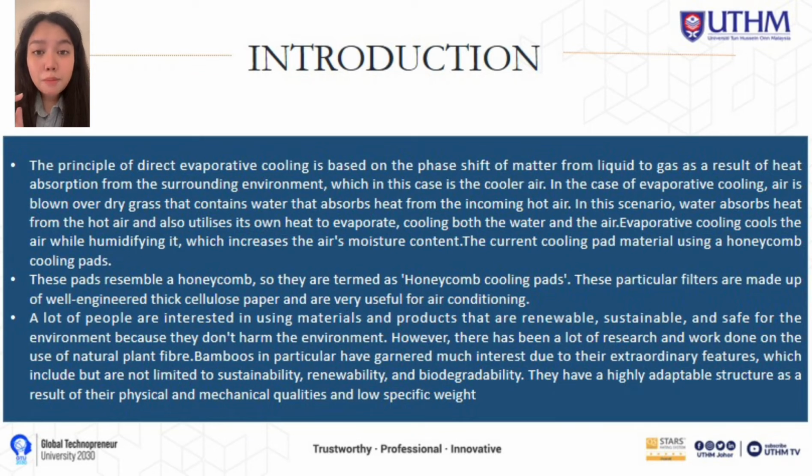The selected material should possess a huge water absorbing and holding capacity, increased porosity, huge flow area, reduced weight, higher thermal conductivity, be less costly, non-corrosive, and easily available.